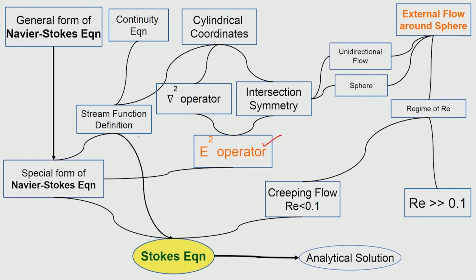Now, so this is done and this is done, and when we see the Navier-Stokes equation, we have already seen that you have got the terms that would have the Reynolds number with the diffusive term, and here you have got the transient and the advective terms, and we have got the pressure drop term, and then we have got the body force term.